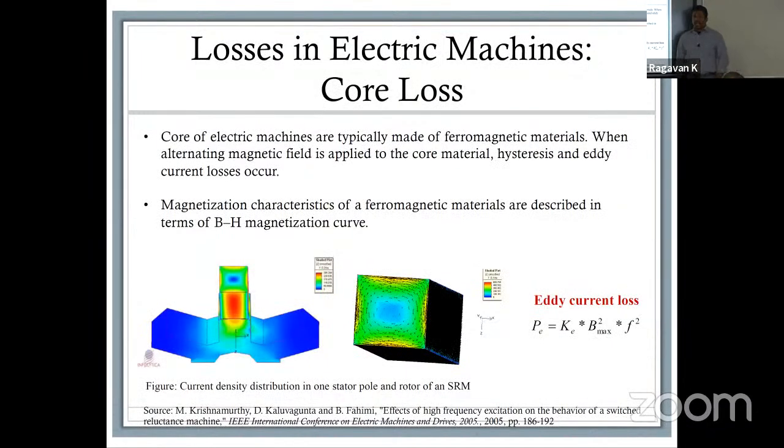So the same thing can happen also in your core. We actually have an article that we published quite some time back, which looks specifically at the idea of magnetization. This is for the eddy currents that are present inside the core. You will see that the middle of the motor does not see the current. This is the current density inside the machine, so what you're seeing is the surface current density. Keep in mind, eddy current is a surface phenomenon, which means in order to reduce that,